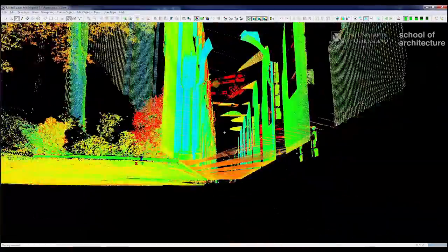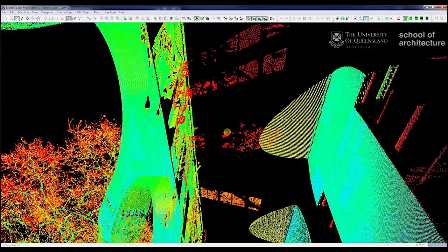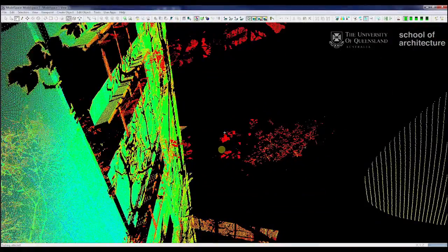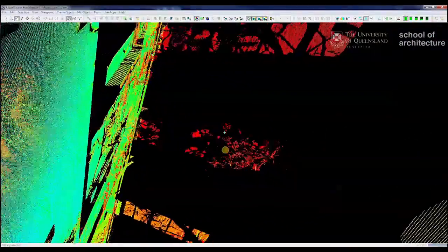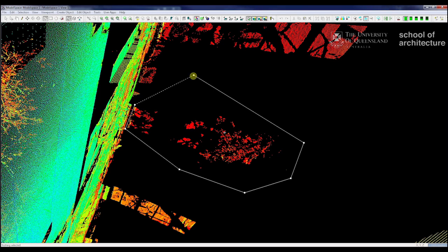isolating it, so we want to get it underneath here, so we want to remove these ones. This way, okay. Get that, yep, there we go. Nice and clean, so we're not removing any good data as well. Then we use our fence tool, use our polygon fence mode, and we select around our various data. If you select something wrong, you can clear it using the clear fence.